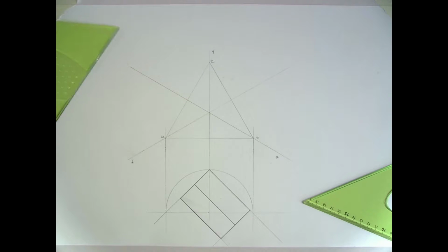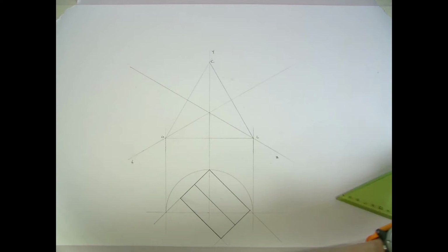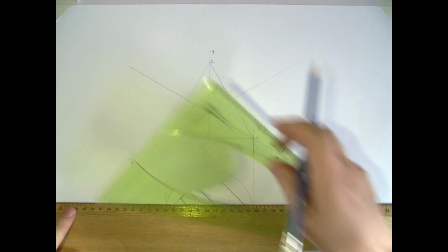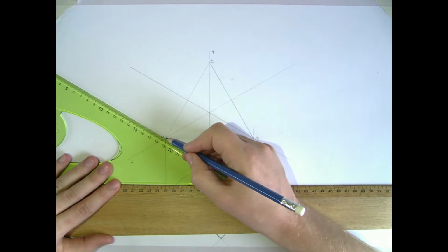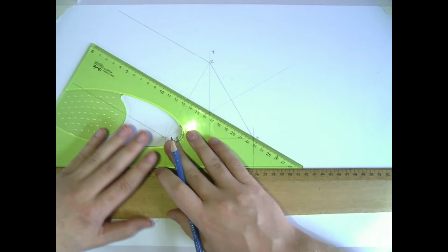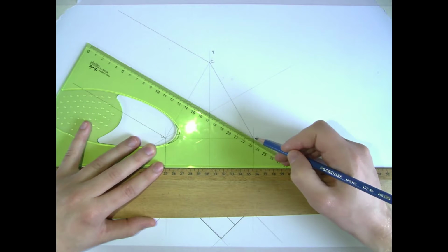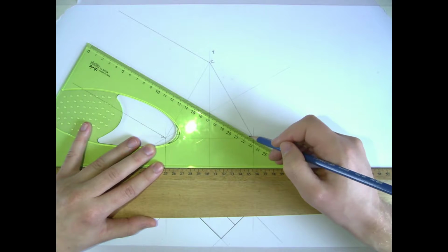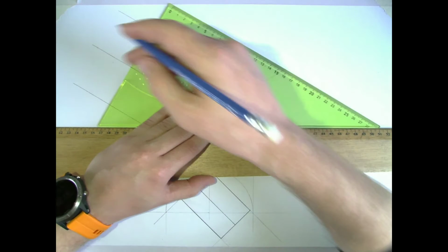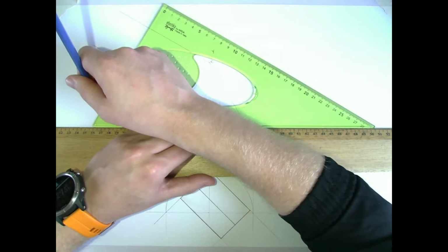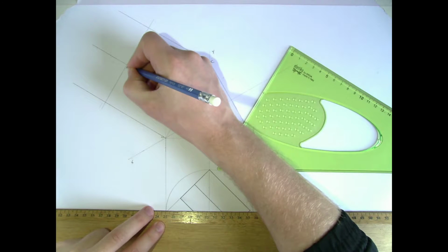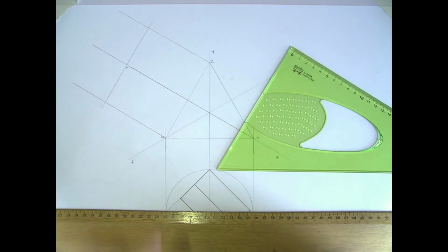So the elevation is drawn up in the top left corner, so we should have plenty of space for that. Again, we're going to do much the same as what we did down here. We're going to extend the lines from A and C out along, and also the axis line, which is Z, and then out along here somewhere we are going to put in our semicircle again. So we need our line that's drawn perpendicular to the line from the Z axis.